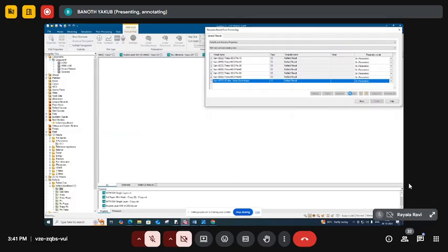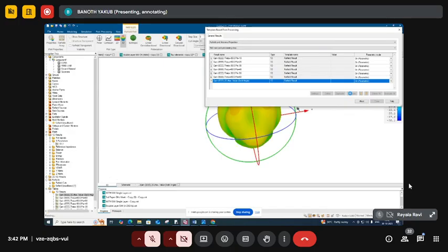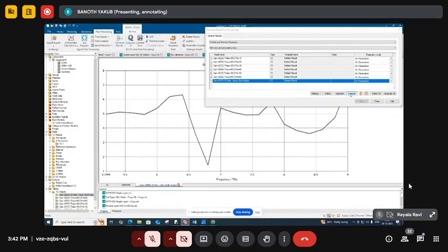So within the 3 bands, 1 band is matched below 3 dB at 7.2 to 7.4. So our antenna design is circularly polarized at 1 band. The remaining 2 bands are linearly polarized, but we have not seen the phase angle changed up to 150. After changing to 150 degrees, I think the 2 bands will also match our actual output. So for any antenna designing in gigahertz or terahertz frequency, you can target any research or R&D for circular polarization or not.